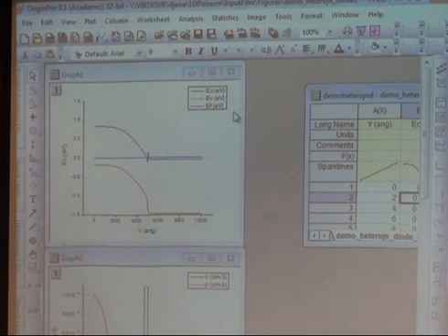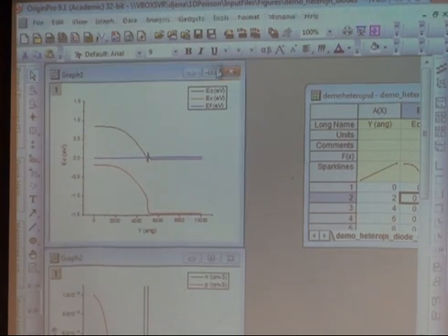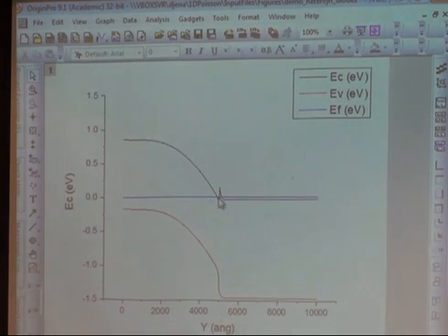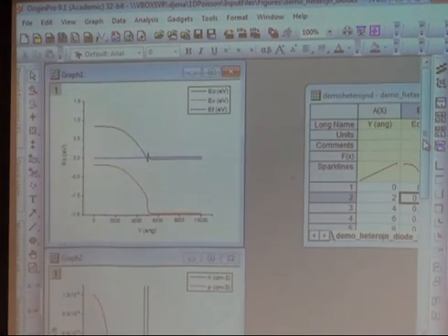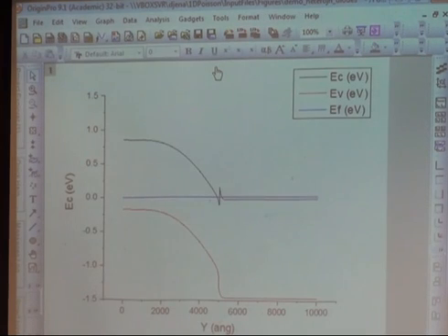All right, see now what has happened. It looks a little bit like that, right? You see the band has gone down here into the Fermi level. So there's a quantum well formation on the left side. You see that? But you know now that from here, you can look at the fields and the charges and all that. But you remember, because you have formed a quantum well, I better turn the Schrodinger around now, right? Because otherwise it's not accurate, because it's solving it classically, but actually it is a quantum mechanical problem within that little window here, right?